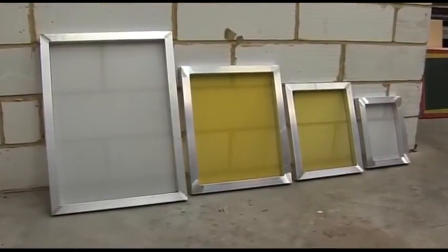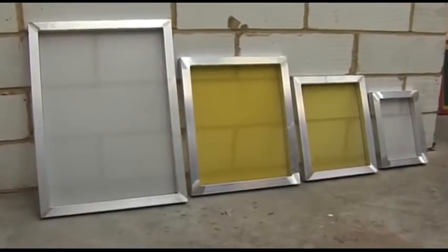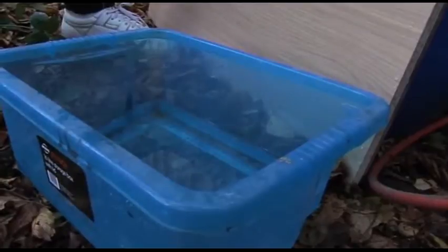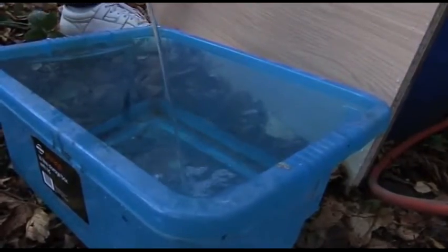Before you coat your screen, you must degrease it first. This removes any unwanted dust, inks and chemicals from your mesh, possibly left from your previous job, for better bond of your emulsions. Wicked Printing Stuff Degreaser has a fresh odour and is ecologically sound and drain safe. Dilute your degreaser 1 part degreaser and 50 parts water.